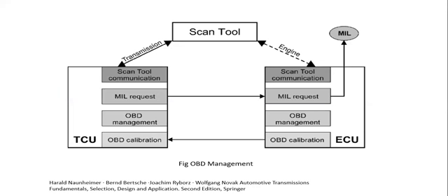And next, the scan tool is nothing but the OBD management, which we'll be using in order to measure the emissions. So every assembly group in the powertrain is relevant to OBD as soon as it exhibits its own control unit. This brings the transmission into the OBD's focus as well. For example, faulty regulation of the torque converter lockup clutch of a conventional automatic transmission can have a negative influence on consumption and exhaust gas.